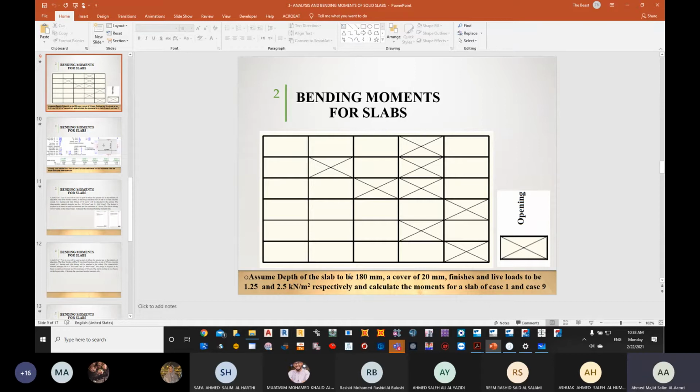You need to calculate the effective depth using the general equation of effective depth, which we are going to take later. Now, if it's not there, you need to estimate. So I cannot estimate an overall depth or effective depth whenever the depth has been given already. Estimation will only be allowed if the data has not been given for you.